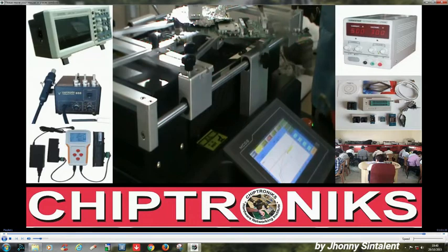And now the infrared temperature is 165 and the beep sound has come up. So we don't have to do anything, we just wait for 10 minutes after finishing this profile, and then we can remove the PCB and test and inspect it.